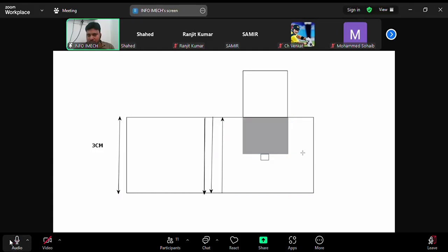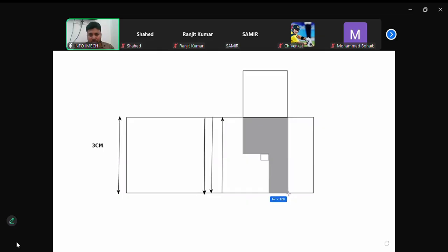Guys, is the total sound reflecting and touching the defect? No, sir. Only some percentage of the sound is touching the defect. The remaining sound is going backward to the back wall. While some sound touches the defect, at the same time the rest goes backward. So sound will reflect from two places: some amount from the defect, and some amount from the back wall also.